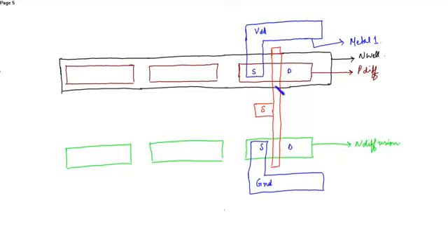Now after connecting the VDD and ground, next you have to connect the drain. And this is S bar. After constructing the inverter, the inverter part is finished except the contacts. So you can complete the transmission gate, or if you want then complete the inverter first by placing the contacts.